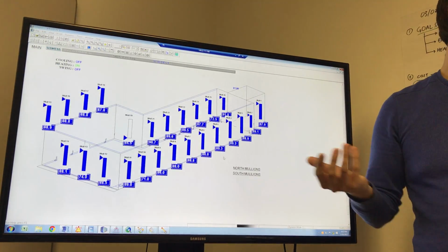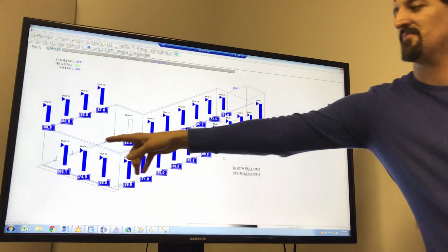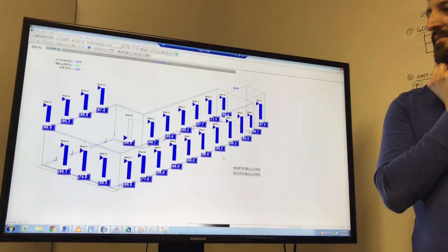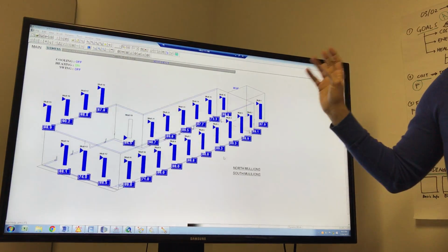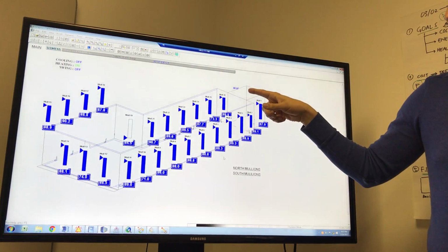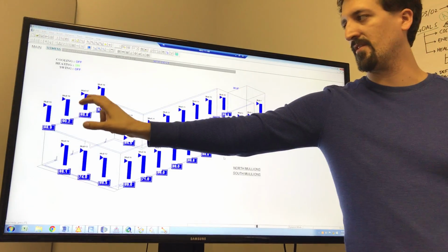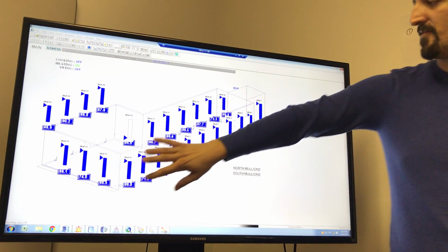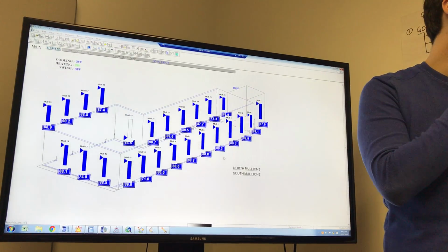Yeah. No, because we don't need it, it's a stair. Stairs, no need, and you want to save GPM for the remaining ones. Right. So one day, if it's extremely cold and somebody complains, you feel like you blast temperature but you cannot get it, and nobody's in the north, you can start to close this and redirect the whole heat. You can do this. And we have done this in the past.